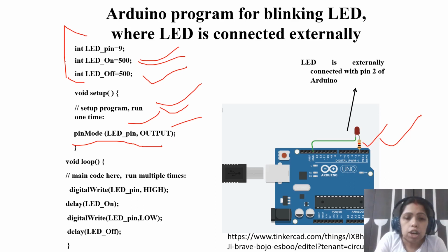Okay. So you are sending data. For that, digital write is required. That I have also told, right? For sending data, the pin will act as the output, and the write function is required for sending the data. Okay. So digital write within brackets LED pin. The LED pin number 9 I have typed as the LED pin, and logic 1 means high. I have to write the high, that means logic 1 I have sent.